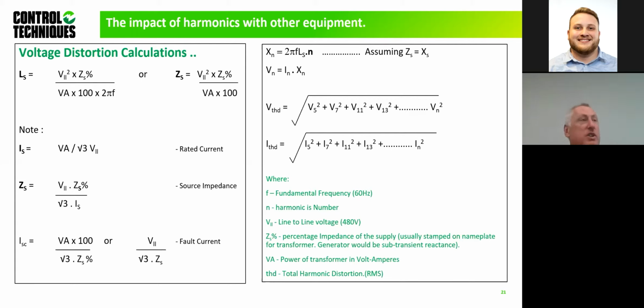And this is the challenge here with voltage distortion: if you don't know what you're connecting to, it can be a problem. But again, if it's a critical site, especially downtown areas, you can take a place like New York, London, etc. They're going to have very high levels of distortion anyway. So they've got a challenge to keep the distortion levels down. Usually you should get more information available to you, because again, I'm trying to minimize or eliminate the existing harmonic levels, or not increase them, because from your TV sets, etc., it all adds into this larger scale harmonic distortion on the grid. So again, we'll talk a bit more about how we can minimize that later.